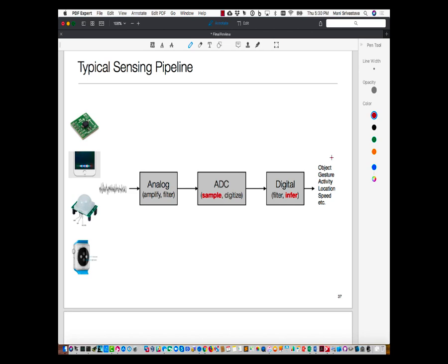Approach number 2 was to use a model. That is, based upon recent history, we make a prediction. What is the next good sampling point? If I see the signal was changing very rapidly, then I would be very conservative and sample quickly. If on the other hand we saw that the signal was changing relatively slowly, or is expected to change relatively slowly because maybe I have access to a model, then I'm going to take a longer step.